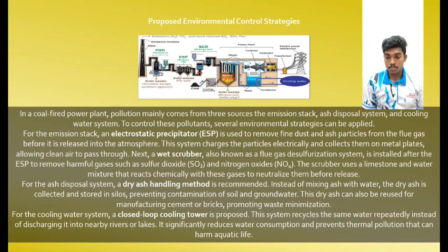For the ash disposal system, a dry ash handling method is recommended. Instead of mixing ash with water, the dry ash is collected and stored in silos, preventing contamination of soil or groundwater. This dry ash can also be used for manufacturing cement or bricks, promoting waste minimization.